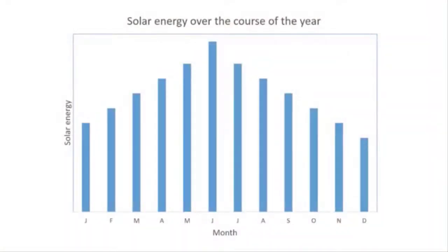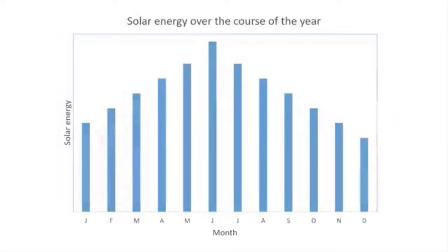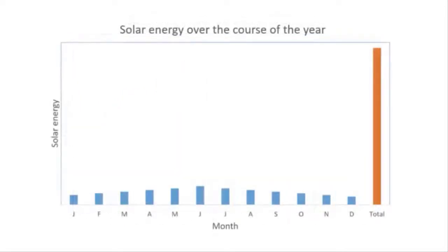So why is this all important? Well, a solar module can produce a specific amount of power based on sunlight levels, and that amount of power varies constantly based upon weather and seasons and day or night cycles. Because that power level varies, the only way to know how much electricity is produced during a year is to calculate the sunlight power over time. That's energy. Energy values can be summed over a time period to get the total energy used or produced. This helps us compare the energy demand to the energy production. So how do we put this all together?